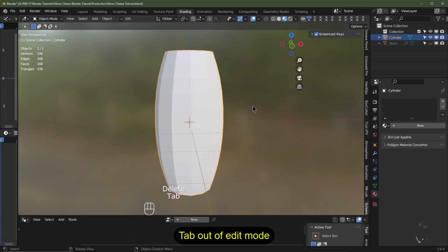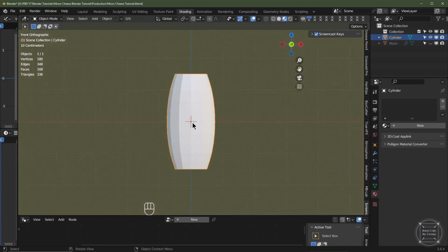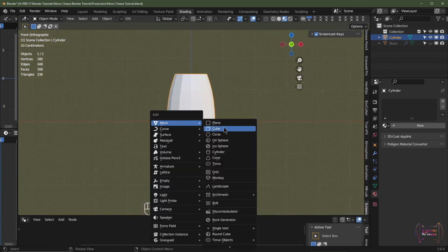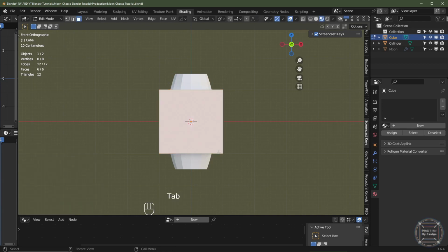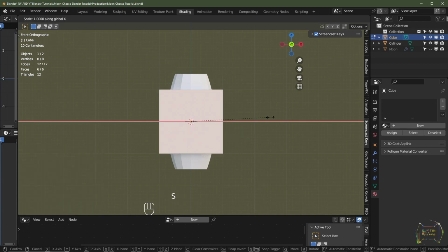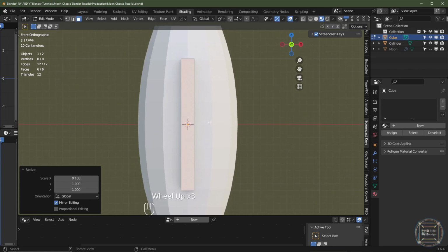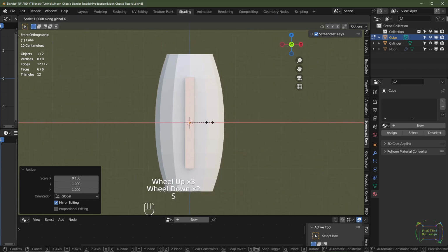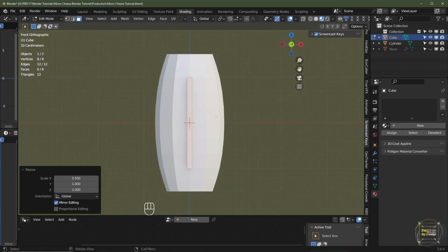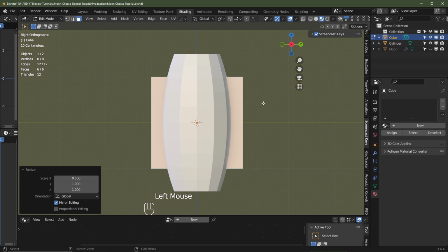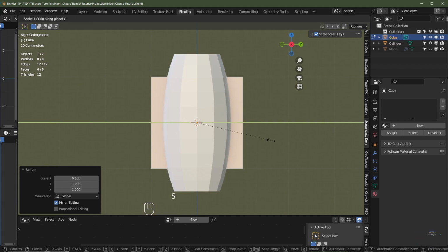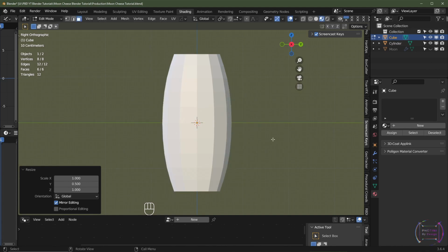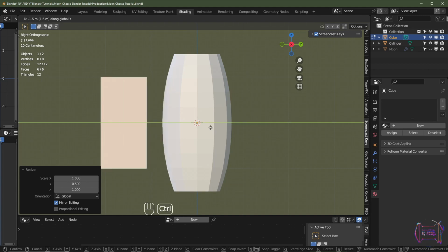Let's add the fins. So I'm just going to hit Shift A, add mesh, and we'll go for cube. I'll go into edit mode, I'll select all, I'm going to hit S X .1. That's still a bit thick, so S X .5. Okay, we'll hit numpad 3 to go into side view. If you haven't got a numpad, you can always select this gizmo here. So I want to view it from the X axis. I'll then hit S Y .5. Hit enter, and then I'm going to hit G, Y, and I'll just drag this out